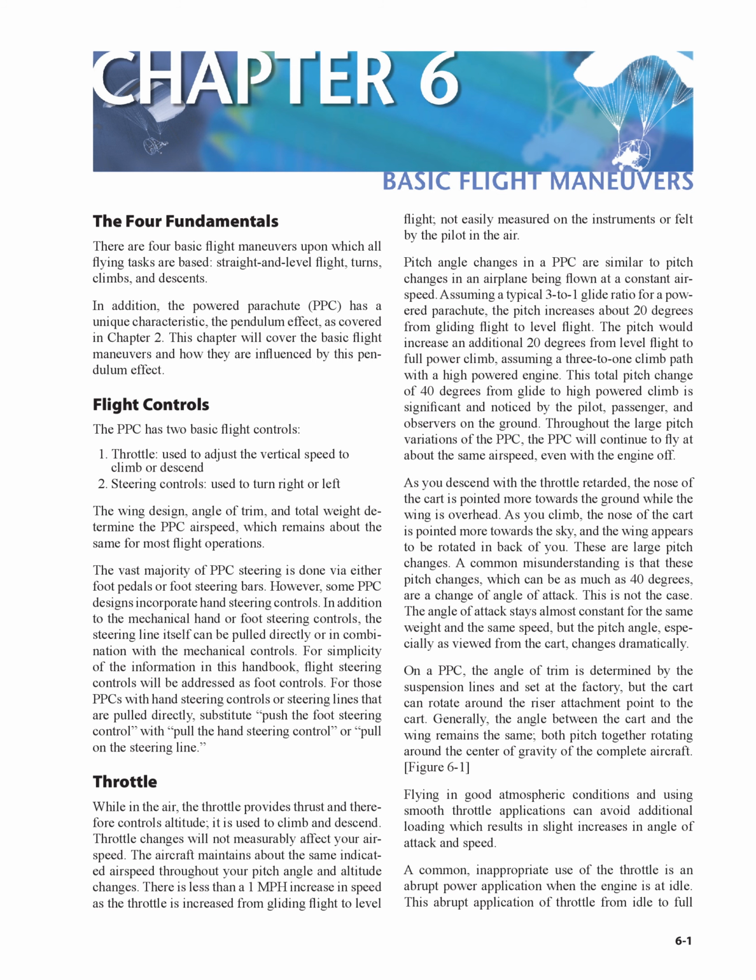A common misunderstanding is that these pitch changes, which can be as much as 40 degrees, are a change of angle of attack. This is not the case. The angle of attack stays almost constant for the same weight and the same speed, but the pitch angle, especially as viewed from the cart, changes dramatically. On a PPC, the angle of trim is determined by the suspension lines and set at the factory, but the cart can rotate around the riser attachment point to the cart. Generally, the angle between the cart and the wing remains the same, both pitched together, rotating around the center of gravity of the complete aircraft.